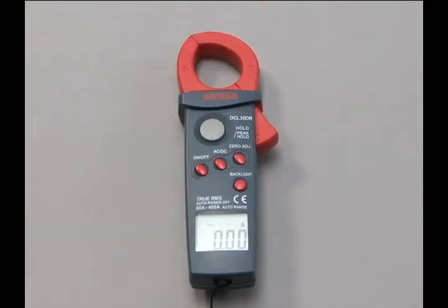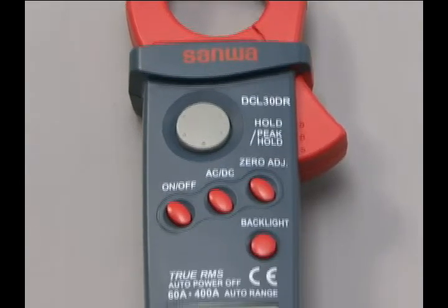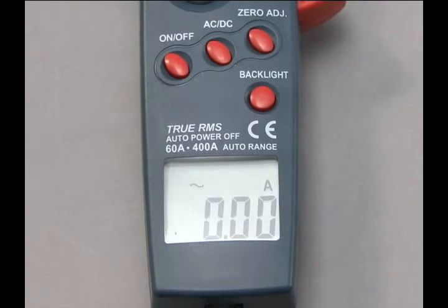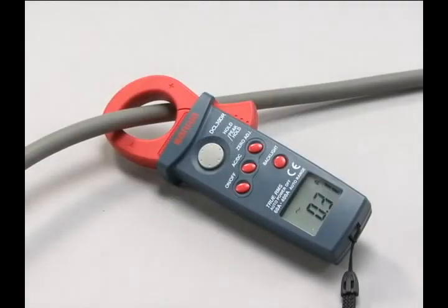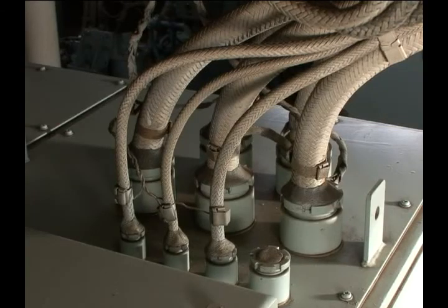It is possible to use a clamp meter to measure a heavy current like the one passing through the motor. Current flowing through the cables can be measured by a clamp meter without having to touch the cables. This means that current can be measured without having to turn off the equipment being checked. However, the clamp meter cannot accurately measure current flowing through basket-armored cables. Use this type of meter at parts that are free of armor. Now let's confirm the points to remember when measuring current with a clamp meter.